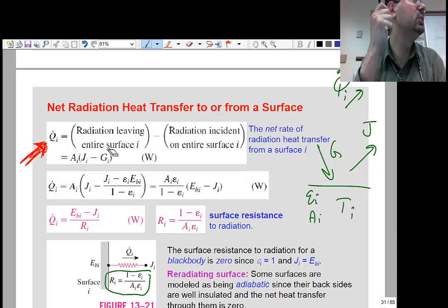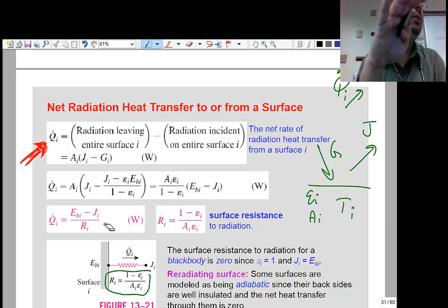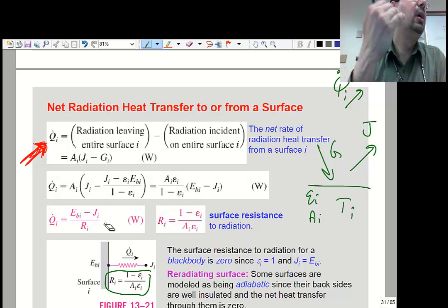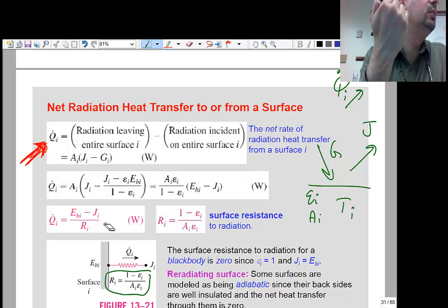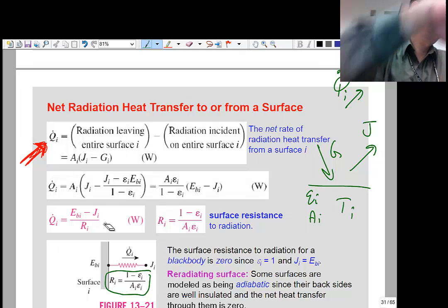Okay, that's his own radiation. There are different levels of black body. I understand the radiation is one for a black body, but there are different types of black, like a big black tar compared to a black piece of paper. So a black body is actually nothing in real life. It is the idealization of a perfect emitter. The tar will not be a black body. Not everything that's black has epsilon equal 1. This T-shirt doesn't have epsilon equal 1. All right.